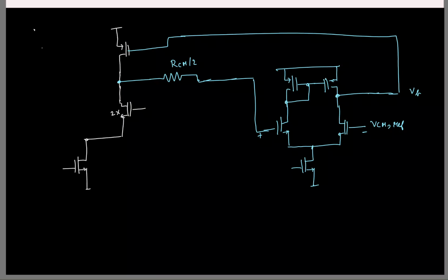So now please look at the circuit and tell me if it resembles something that you know already. Huh? What is gate booster? Oh, no, why is it gain boosting? Gain boosting, we need to sense from the source and give it to the gate. The same thing, right? We have to sense from the source and give it to the gate. I mean, okay, fine. This is a negative feedback loop, right? Okay, let me make it easier. I'll break the loop. Now look at the circuit. This is my 5 transistor OTA.